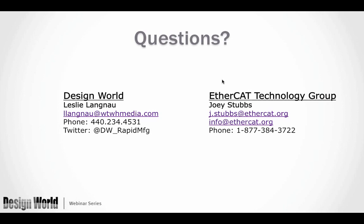And he's giving an example of 40 gigabits per second. Right now, EtherCAT is 100 megabit per second only. So that's in the future, as the need for faster systems continues to grow, then EtherCAT will probably migrate to those. But at this time, for automation, 100 megabit EtherCAT is much faster than gigabit Ethernet protocols, for instance. Most gigabit Ethernet protocols, if not all. So controlling hundreds of axes in the microsecond range, millisecond range is all that is required these days. So we'll be there when it's a necessity for automation, but 40 gigabit is a pretty specialized animal right now.